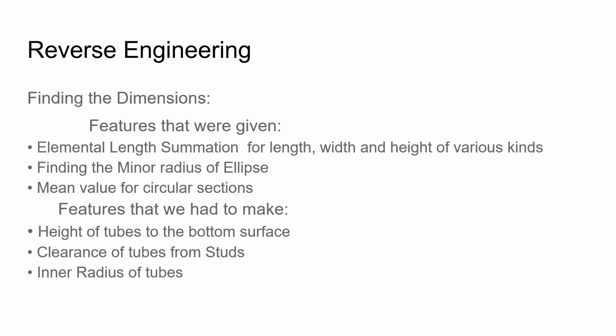We then proceeded to look into multiple methods of stacking. We noticed that the shell thickness during the measurements of the brick was about 1.2 mm, which meant that the interior of the walls of the brick, when stacked together, did not make contact with the studs. So we had to do some kind of projections to solve that issue.